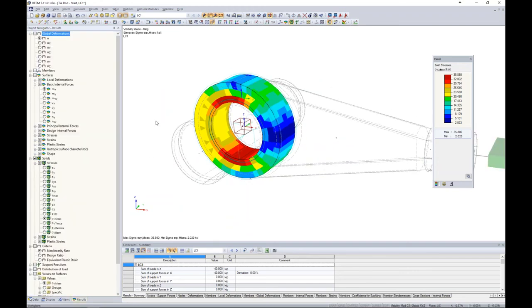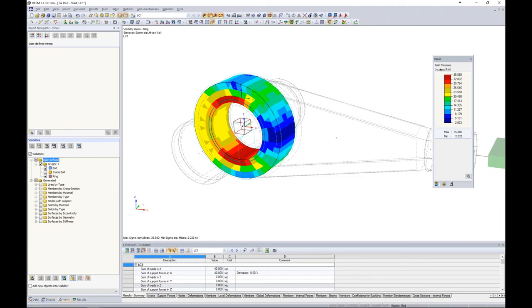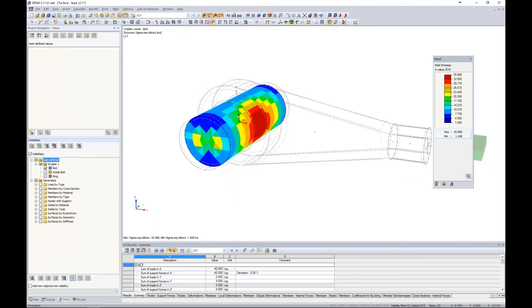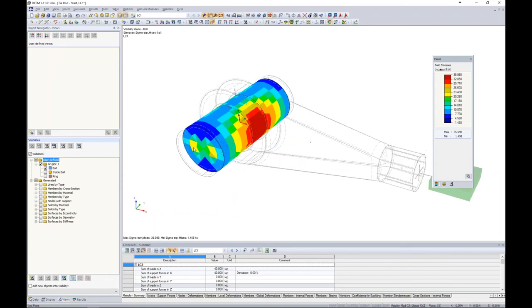Now, the other thing to notice is that under the bolt, if we just generate this view, maybe we're interested in viewing what our stresses are along the depth and length of this bolt. And with solids, it's sometimes hard to tell what's going on within the inside of this solid element. And that's where we have something called a clipping plane.